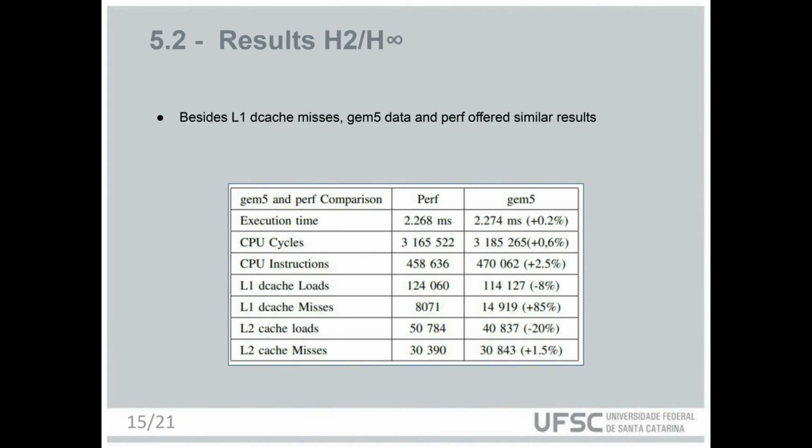For this control program, we also ran some additional tests on the real Raspberry Pi 3 board. We used the perf tool to collect CPU data such as level 1 and level 2 cache loads and misses, total CPU cycles and instructions, and of course execution time.